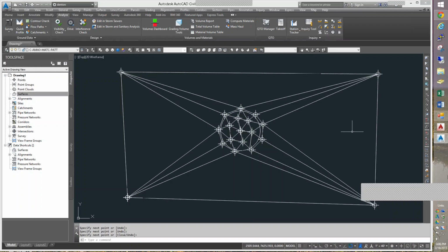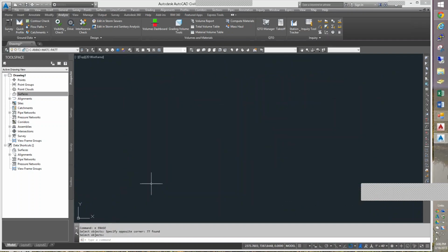Now, if we were to look at a channel, I'm going to just erase all that. I'm going to use a command. I don't know if you've seen this one. Sketch. What it'll let me do is draw a channel for a creek. So I've got the center line of the creek, and let me do the point command. I'm going to turn my snaps off so I can just eyeball, but I'm going to do a point here at the center of the creek.